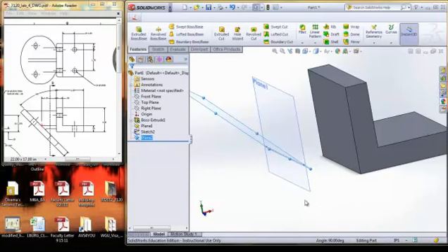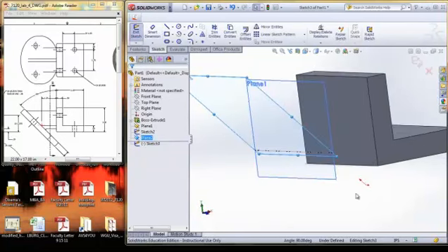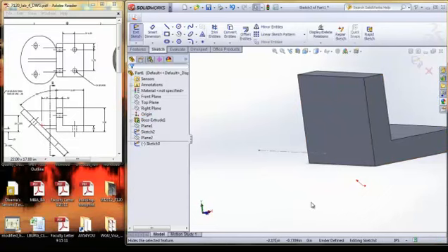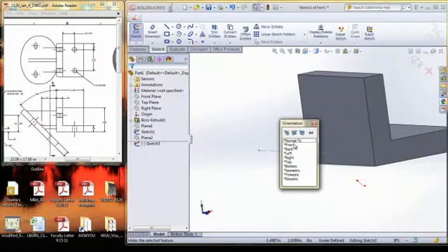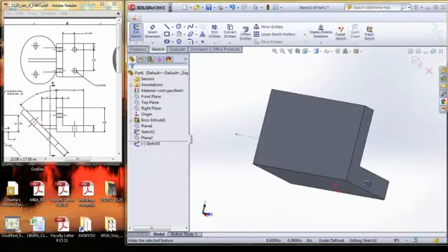And there you have the plane you want to draw on. So then I could go to sketch, hit sketch, and it's picking this plane already, and you can see the coordinate system updated. Now if you want, you can go back and hide that, hide this, and now you're ready to draw. So if I hit the space bar again and double click normal 2, I'm looking straight in on that line. If that's an issue, you can be okay to go like that.